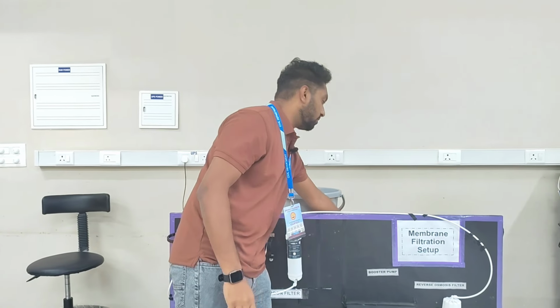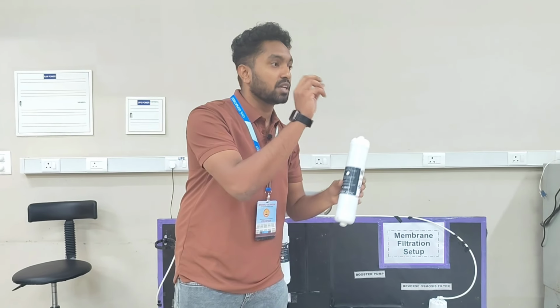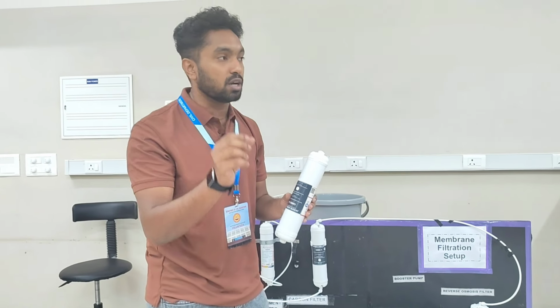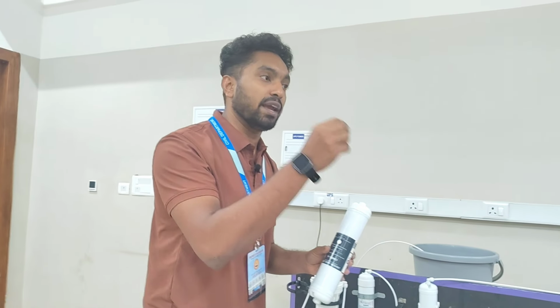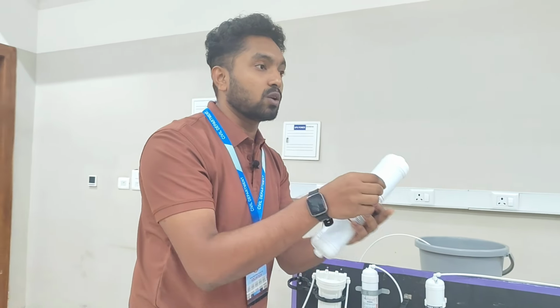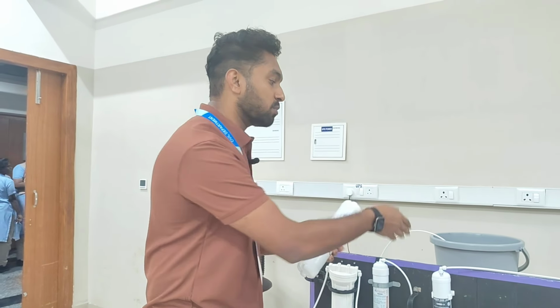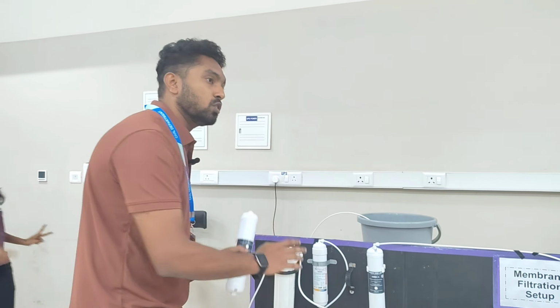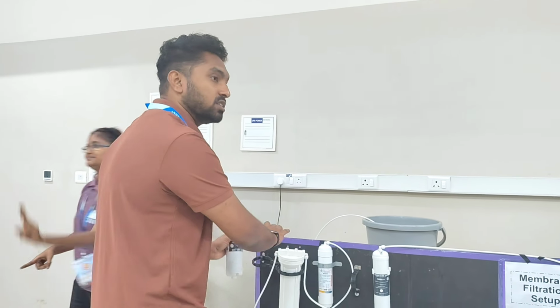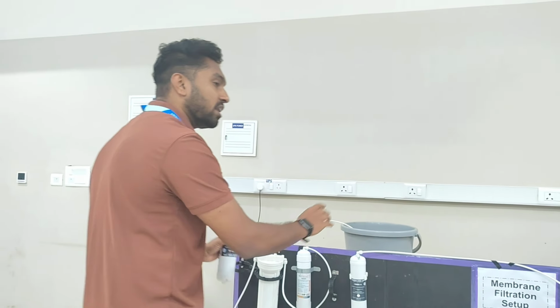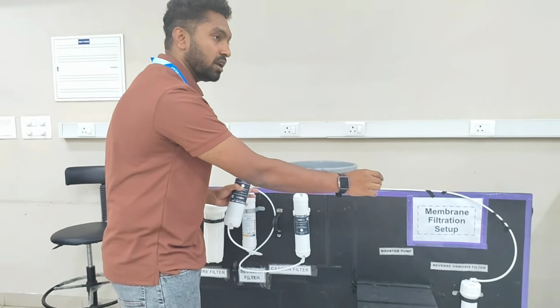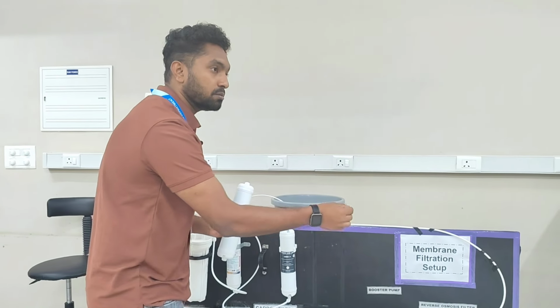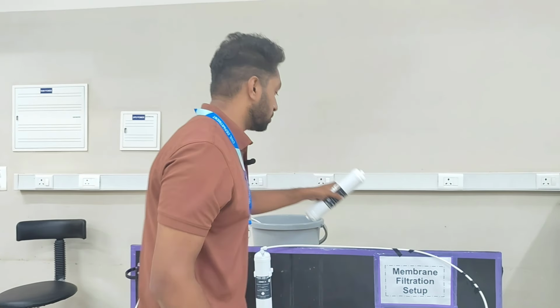In the activated carbon filter, as you can hear, there are grain-sized particles. It has activated carbon in the form of coconut shells, which absorb materials. For example, if we dip a plain cloth in some dye, the cloth gets stained or colored. The same process happens here: it absorbs the dyes or impurities. Nearly 95% of the impurities are removed in these 3 stages, and any remaining impurities, bioparticles or microorganisms are removed through the reverse osmosis filter.